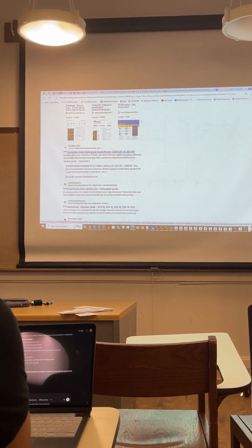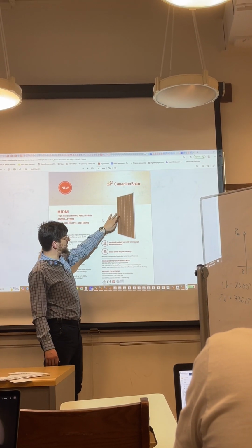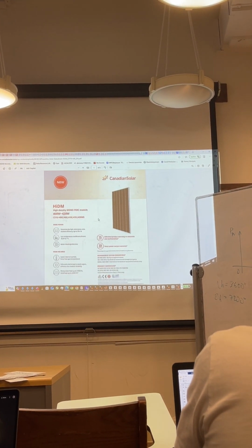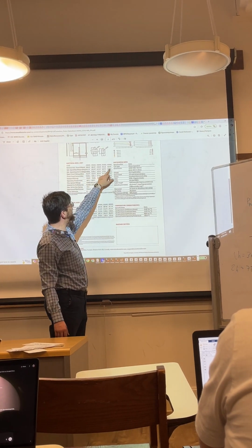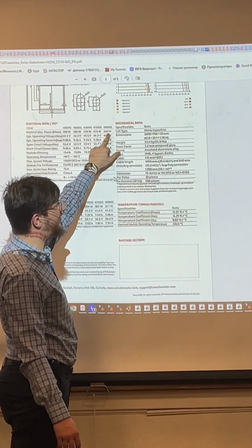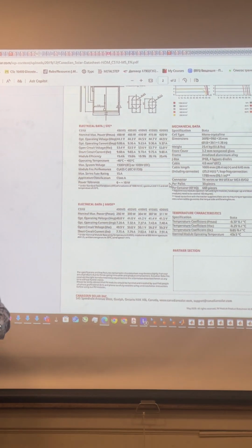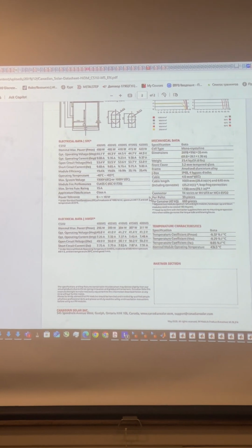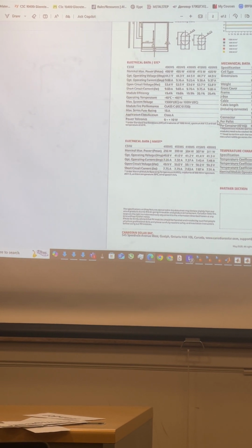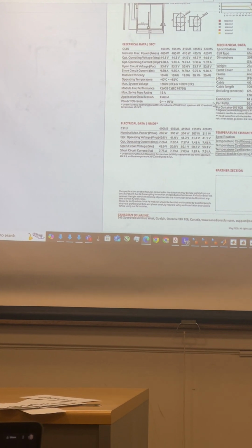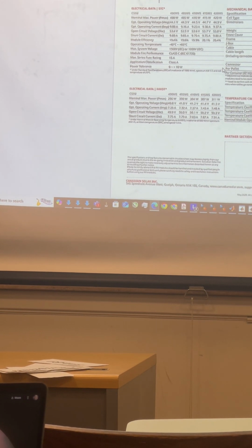Let's just click this one. All right, so this is one module. It has several cells connected in series. Let's assume that we're using a 420 watt module. A 420 watt module has an operating voltage of about 45 volts. This is the symbol of the module typically used in a one-line diagram. It has 420 watt peak maximum output at an operating voltage of about 45 volts.